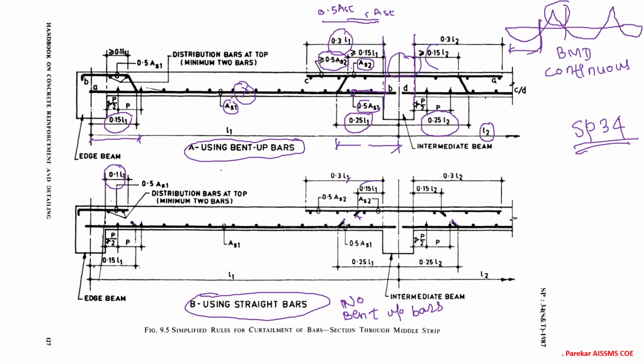You may have a question that shows the bending moment coefficients for continuous beam, and what are the clauses for it, or when we are going to use these coefficients. Then we should be in position to answer. We require minimum 3 spans. The value of the span should be within 15% of it. So likewise, you should be in position to answer the questions about the clauses.